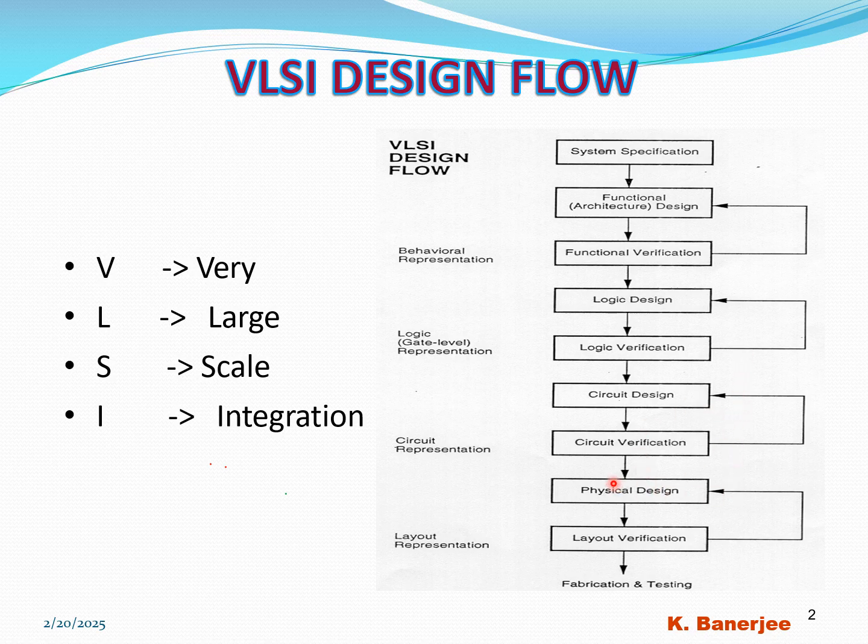After the circuit verification, we have physical design. Physical design is basically the conversion of the circuit representation. That means in this stage, the circuit representation is converted into a geometrical representation, that means the mask design. The geometric representation of a circuit is called a layout. And we have CAD software for layout verification as well.